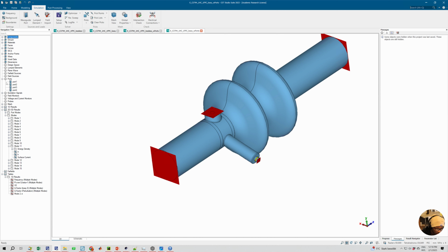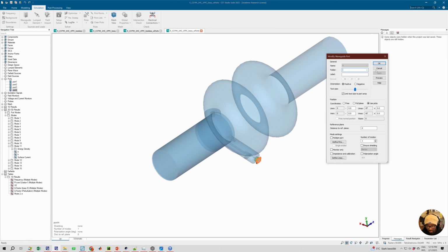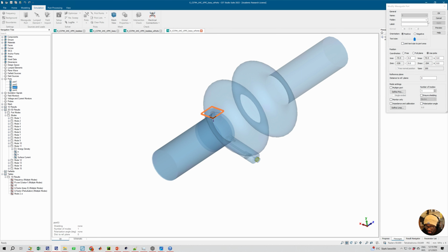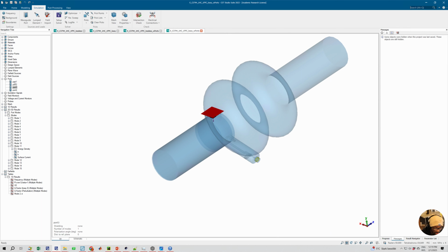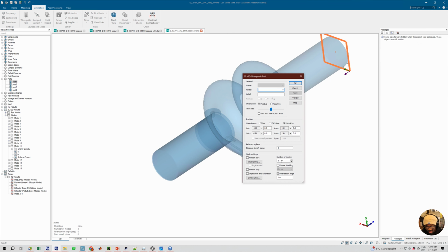So I'll show the port definitions for these. This is just one mode for the TEM line, and port 3 also is just one mode. But then for the beam pipe, depending on the frequency range you are considering, you should consider increasing